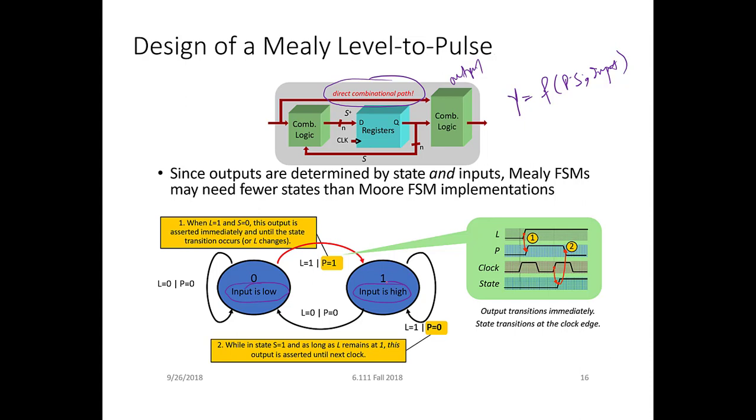Remember that in a Mealy FSM, in most cases, the number of states will be less than the Moore FSM. In most cases, it will be less by only 1 state. The reason for this is that we represent the output on the arc and not inside.